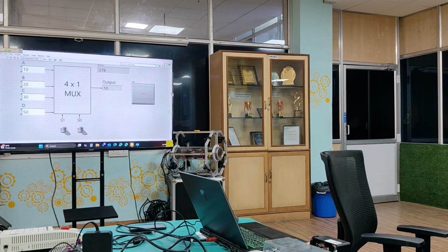Run the program. Check the processor load in the Task Manager. You can feel the difference. It won't display anything, sir. It will slow down your execution. Create one indicator. Right click, create indicator. It will display how many iterations are completed.